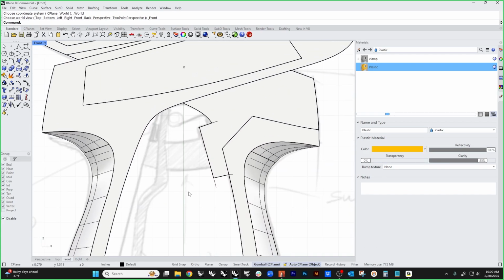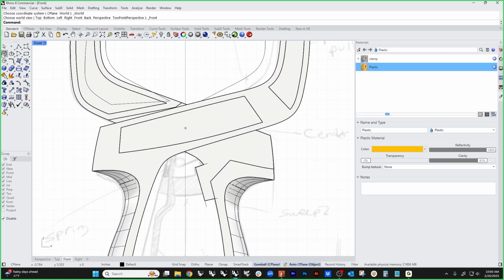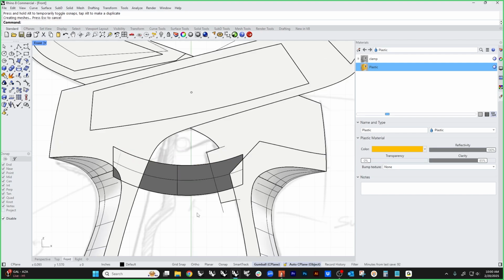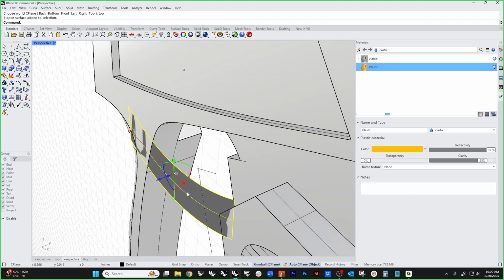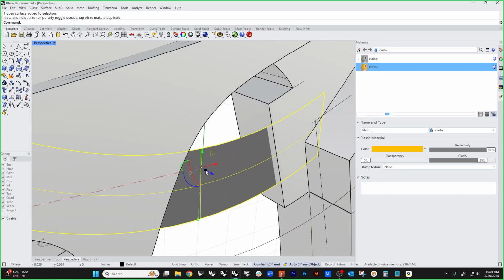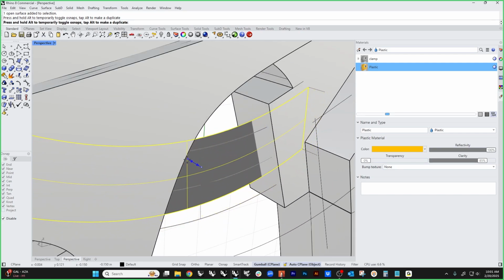And then our little metal piece, let's do that with a 3-point arc. So I'm going to start here and there, go something like that, and it looks like it's a little smaller radius. And I'm just going to extrude that shape up like that. Stick it inside there. Drag to extrude for my thickness.